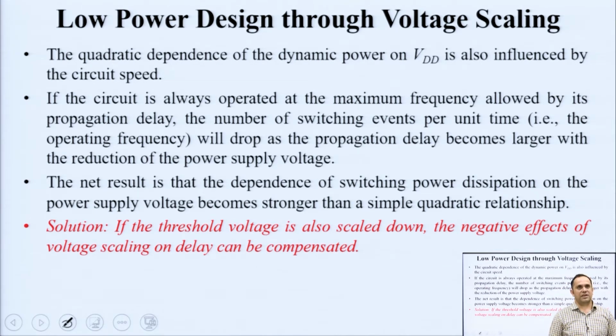What it basically does is that the power dissipation now becomes more dependent on the power supply voltage. So, now I am in a situation where I do not want to leave this trend, I want to do something with the power supply voltage. If I can reduce that and still keep delays to a reasonable value, then I can obtain my objective of low power design.